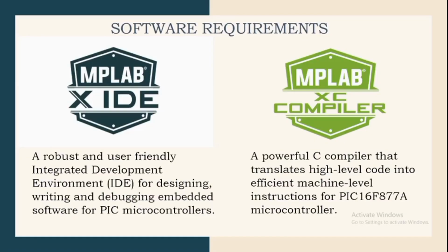For example, in MPLAB X, we wrote the main logic to simulate door control, wash, start, stop, and LCD output. Then we compiled it with XC8 and observed the output in PICSIMLAB, just like how a real system works.